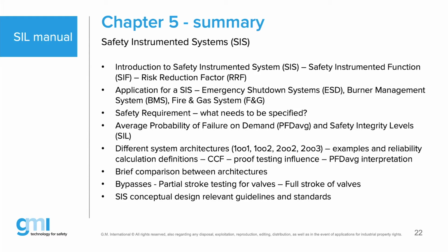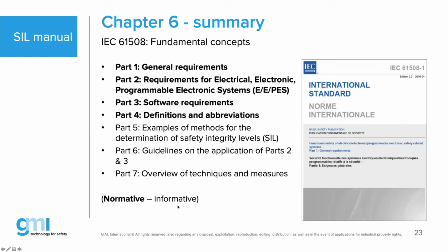What do you have to consider? And how will you compensate? And compensation is a definition coming from edition 2 of the 61511. Bypassing for stroke testing of valves, partial stroke test, full stroke test, and the conceptual design.